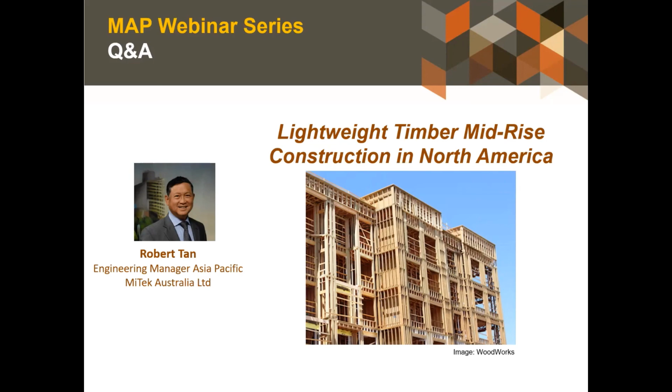It looks like a flattened form of a triple grip or multi grip, doesn't it? And the reason why they look so toothed, when it's basically a nail-on plate like a drag strip, is mainly to reduce the amount of steel in the connector. You don't need all the steel at the top in between the holes, so you can scallop the steel around the holes and nest the way you produce them, so that you have the least amount of steel per bracket. That's the only reason why they look the way they do. Otherwise, it's basically a nail-on plate type of product, really.